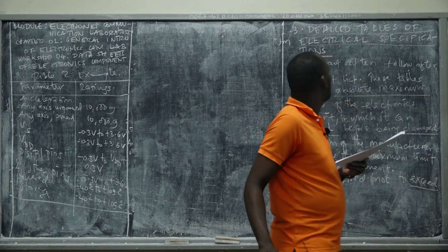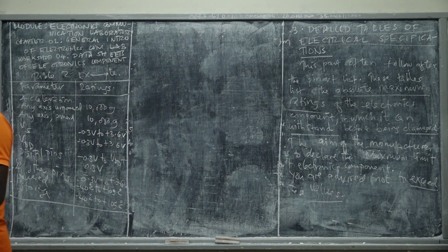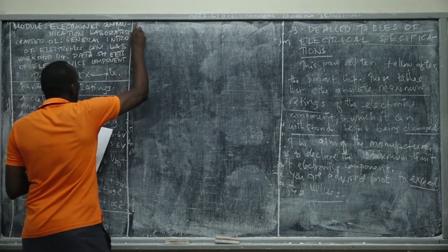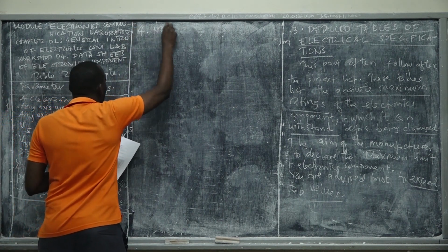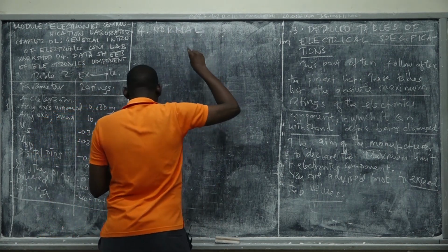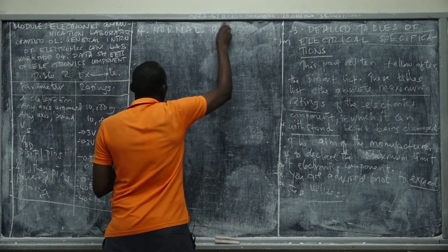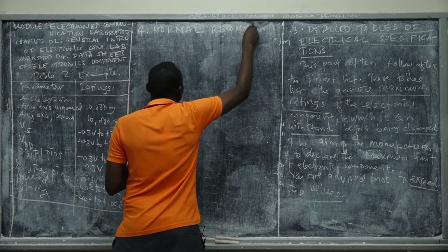The detailed tables of electrical specification give you the absolute maximum rating, but also the normal recommended operating condition for the electronics component.